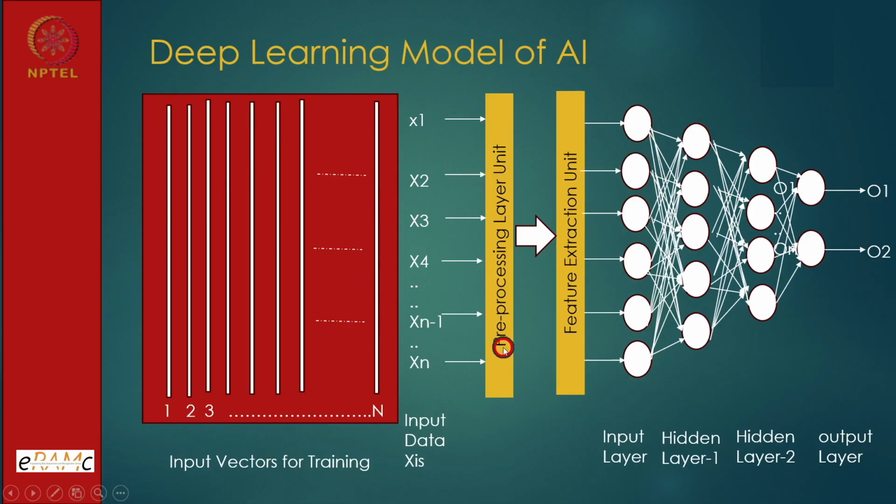They were pre-processed, with the methodology I told you, and features extracted. Sometimes instead of presenting the vibration signature, we can extract the feature and present that to the NN, so a lot of energy will be saved in processing, and ambiguity or fuzziness is removed.